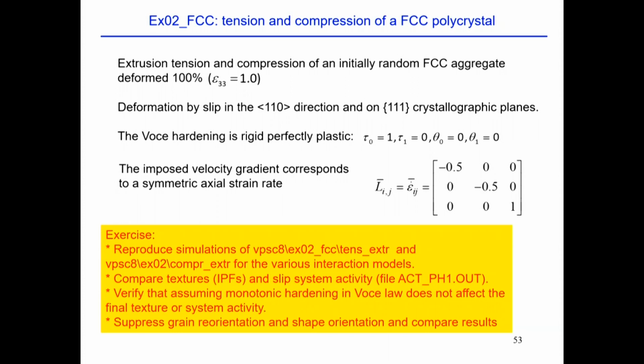Everything that is strain rate, typically we think in 1/s, but you can use 1/hour if you want, because the code in itself doesn't have units. But you have to be consistent when you enter your parameters, so that all the parameters are in the same units.